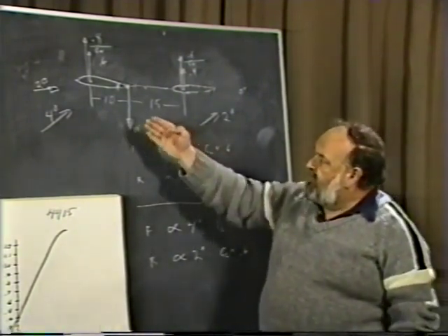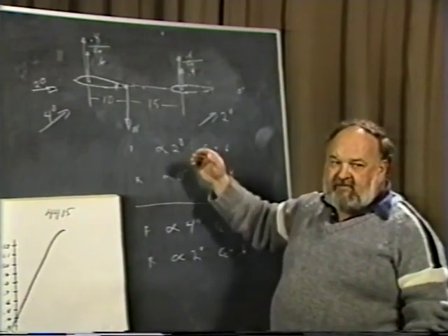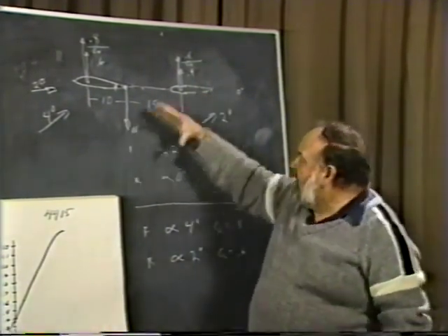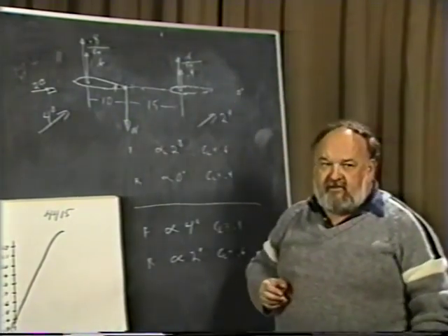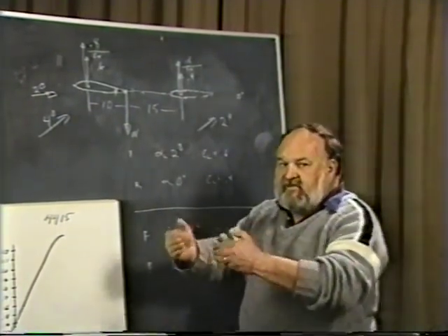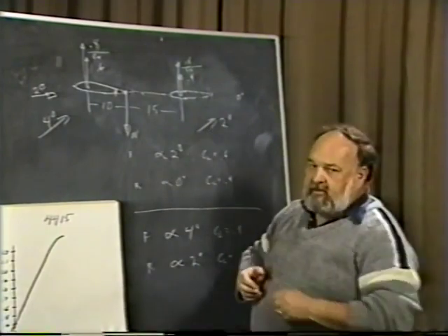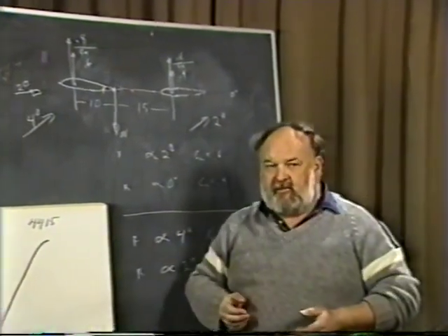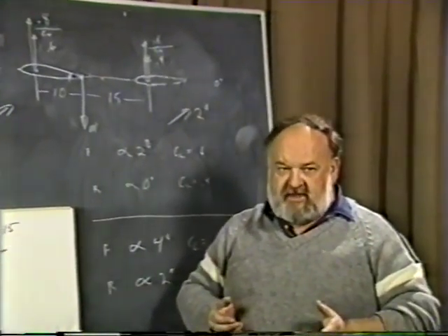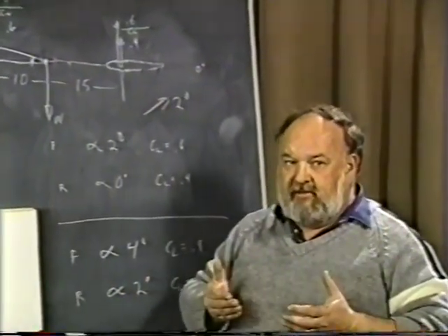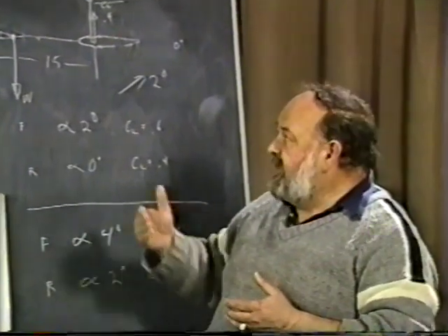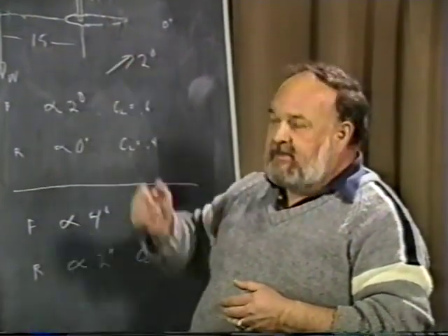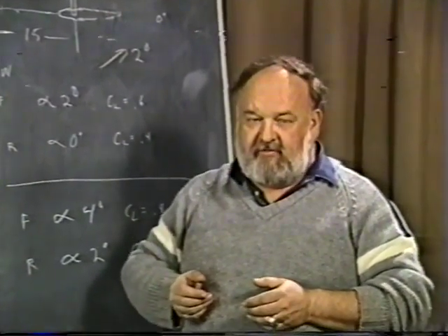And the further we move it forward, the more it would have to be reduced, down to the point where maybe it wouldn't be lifting at all if we moved it all the way forward, even though it's a very, very big surface. Well, you can see, as you move it forward, you're making your tail more and more powerful. That's why when the CG moves further forward on the airplane, it becomes more and more stable. As it moves further aft, the opposite starts to hold true, and eventually you can keep moving back to the point where you have neutral stability, even though the tail is of the same original size you had before.